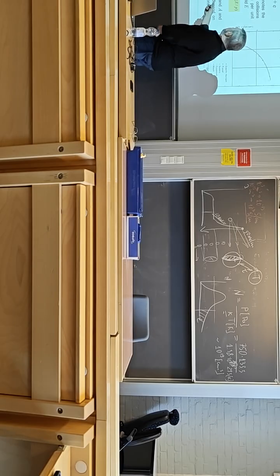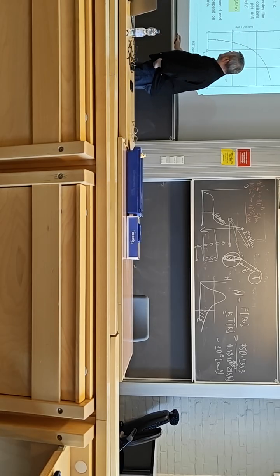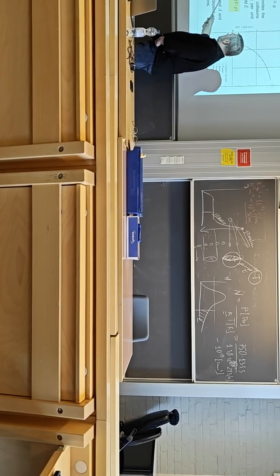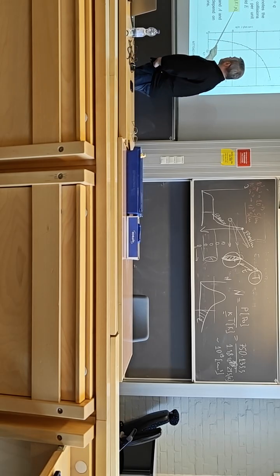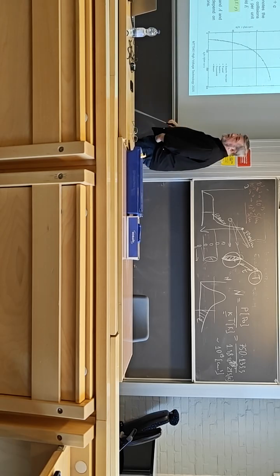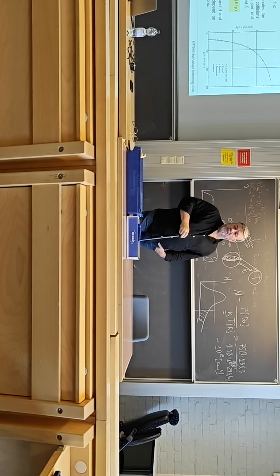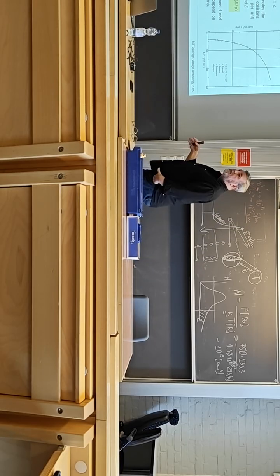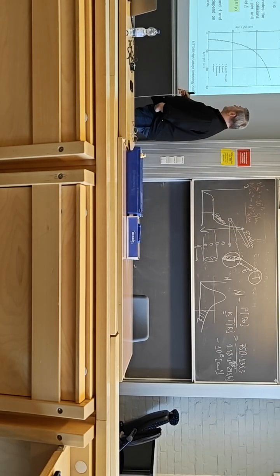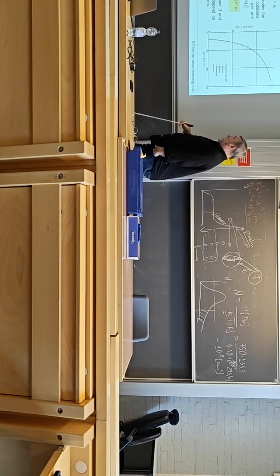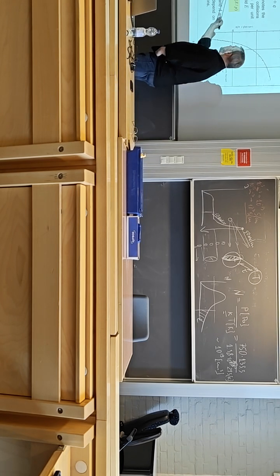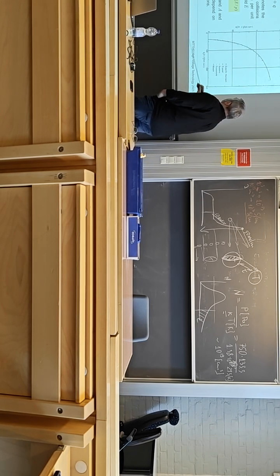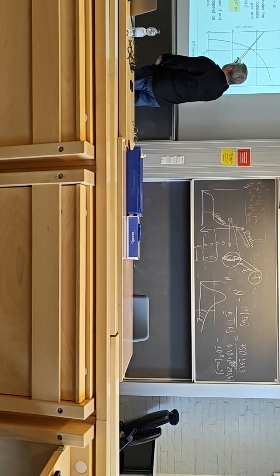It's called the reduced form, so it's divided by pressure. And the field strength, respectively, is also reduced, divided by pressure. It's like for mobility, but for mobility, usually multiplication by pressure is used to have generalized data. For the ionization coefficient, it's divided by pressure. So here is an example.